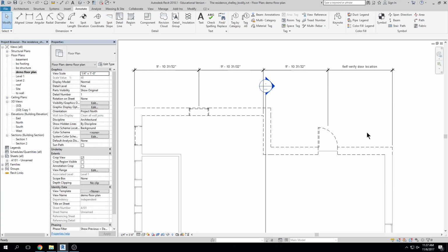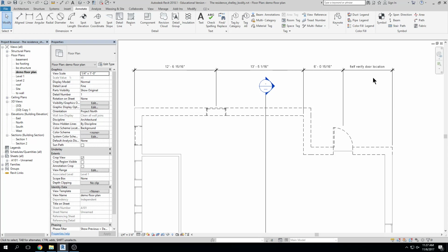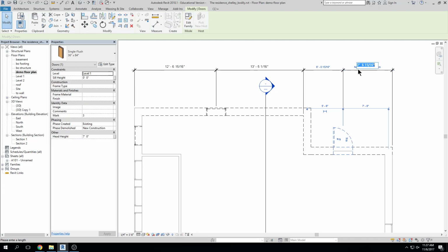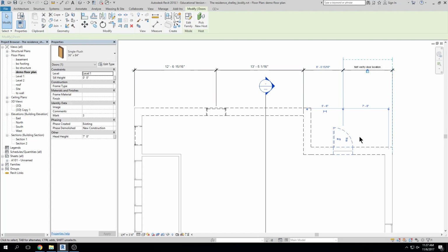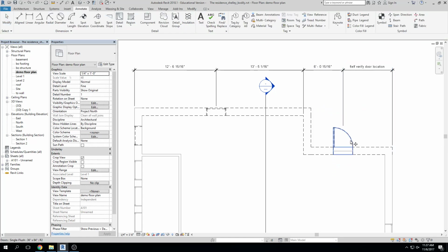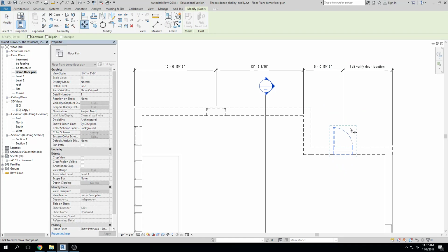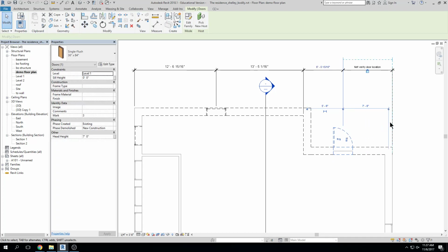I'm going to hit undo here real quick. Okay. Now you remember, I'm going to click on these dimensions again. I placed a constraint on this dimension, so now if I click on my door and I try and move it, MV, see, it won't move it.